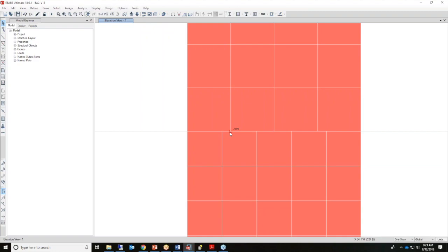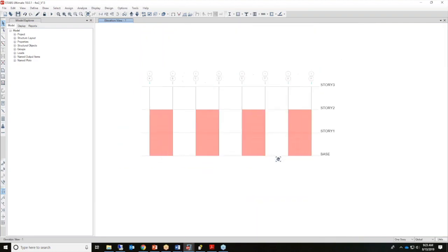These constraints enforce a displacement compatibility between the mismatched meshes of adjacent objects and eliminate the need for mesh transition elements. In years past, in some programs, you'd probably have to put a little dummy element for connectivity here. So we have something called the auto line constraint that takes care of this. Let me show you how this works.